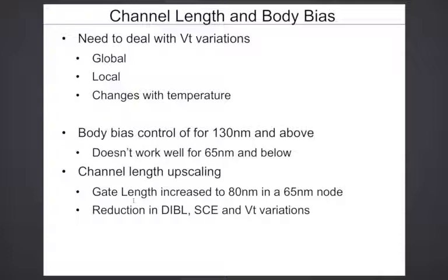the gate losing control of the channel, and the behavior of the transistor, instead of being a square law device, becomes velocity saturated, and you don't have a good behavior of the transistor. Also, as we scale down the transistors in deep submicron, the impact of the body is becoming less, and also in certain process flavors, the body is not even available to you to control, right? So FinFETs and so on.